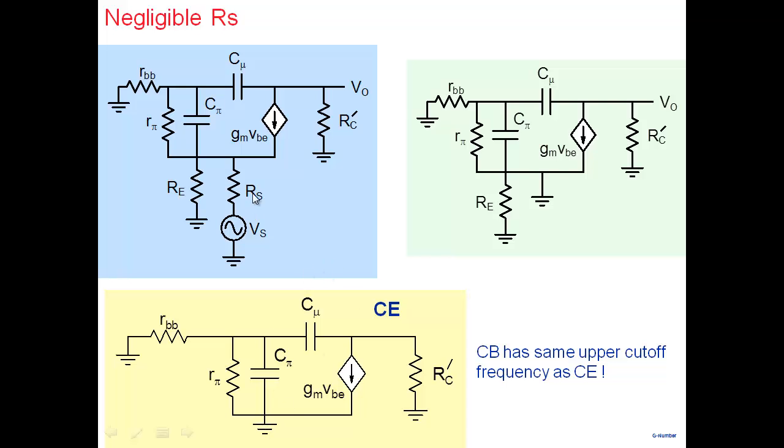When I put a source resistance Rs which is significant, then Rs in parallel with Re will appear over here at this point. This is no longer ground, this is Rs here. And Rs in parallel with Re will appear at the emitter. While here, the emitter resistance is bypassed to ground, so there will be nothing here. So changes occur the moment you put significant source resistance here.